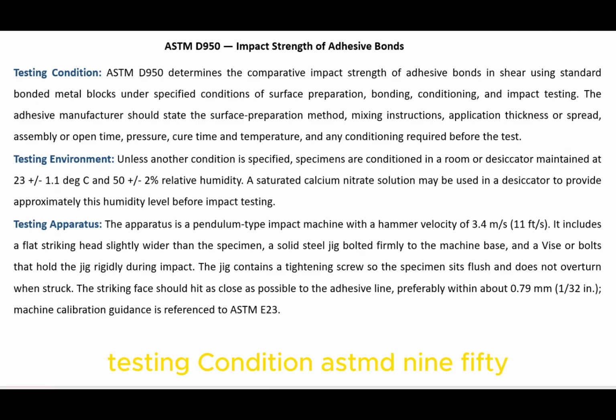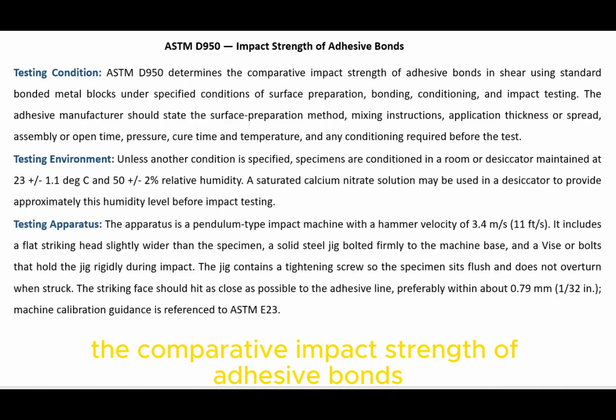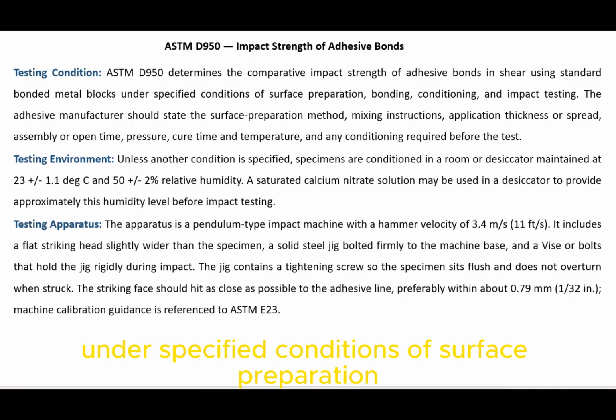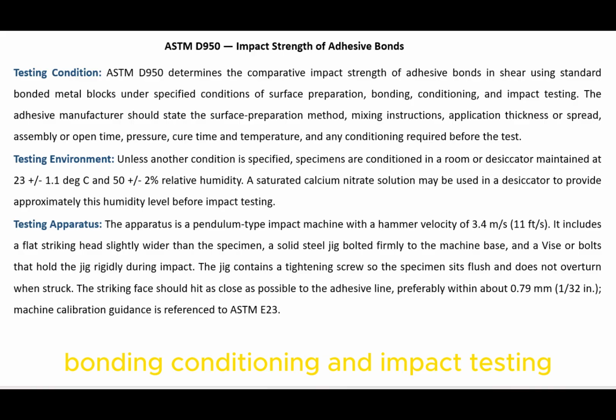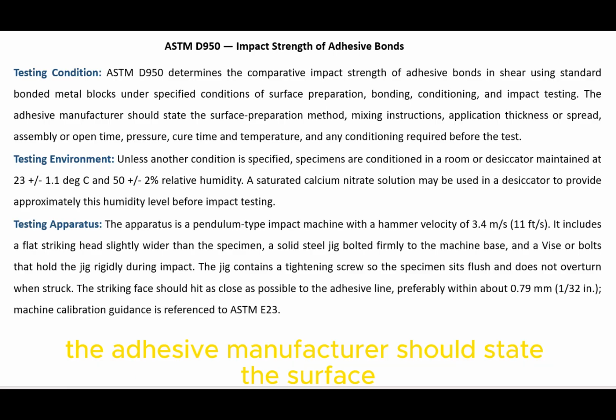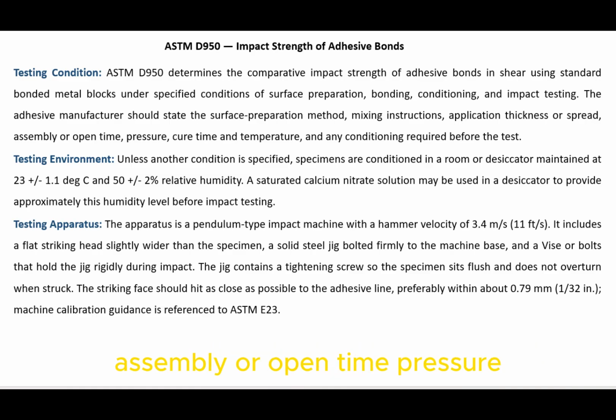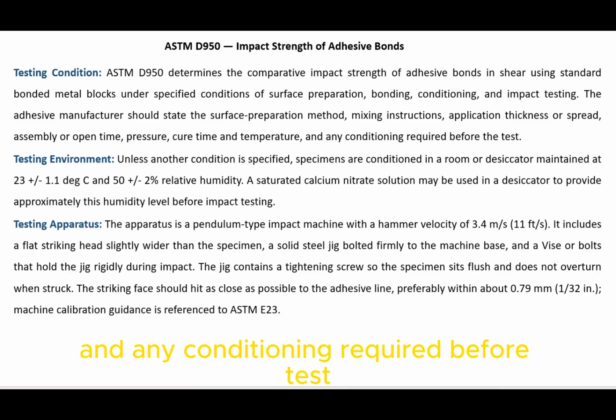Testing condition. ASTM D950 determines the comparative impact strength of adhesive bonds in shear using standard bonded metal blocks under specified conditions of surface preparation, bonding, conditioning, and impact testing. The adhesive manufacturer should state the surface preparation method, mixing instructions, application thickness or spread, assembly or open time, pressure, cure time and temperature, and any conditioning required before test.